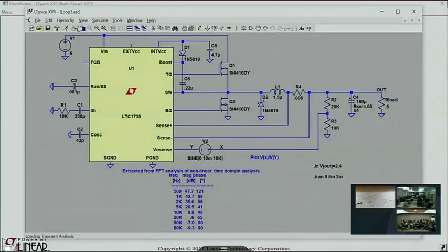See, this is a transconductance from here to here. This is a current. It's either a current or it is not. If you put something with a finite impedance in series with something with an infinite impedance, you don't cause a phase shift. You're regulating a current through the inductor. And that is the whole point of current mode control.